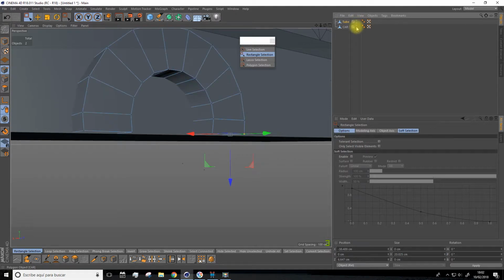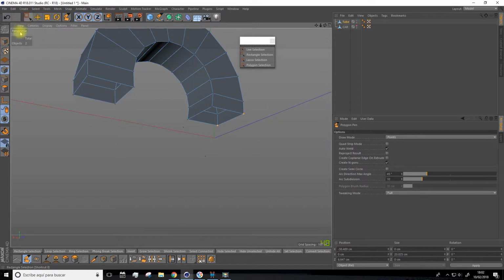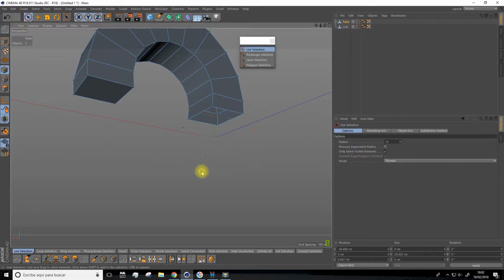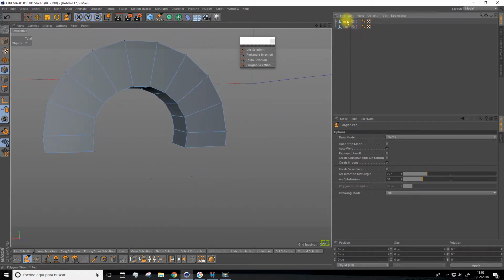We can cover up these holes down here by creating a new polygon. From here to here, and from here to here. Then from here to here, sorry, because I have the point selected. Now again. So we click on each point to create a polygon like this. Perfect.